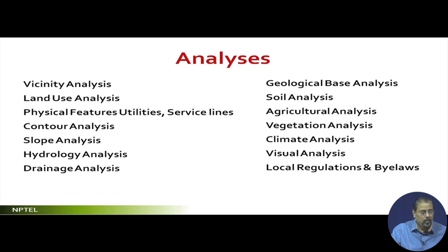Let me go back. For example, in that particular template, you remember, if you are doing the land use analysis, the site diagram, the roads, the plant location of trees, if it is there as a part of the base map, or the contour lines, they will all be common. So that will remain as common, not specific. And for land use, there will be again a set of legends which will be specific to land use, that will not be repeated in others. So each of these analyses will have its own specific set of legends.